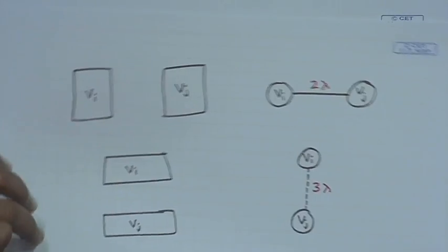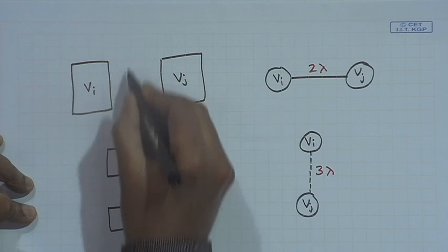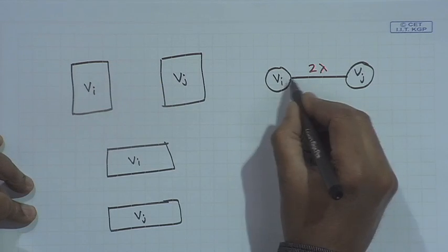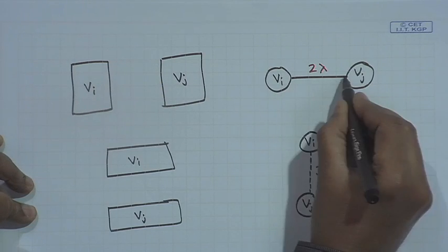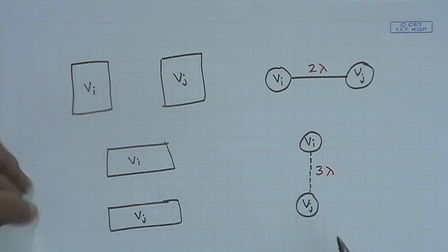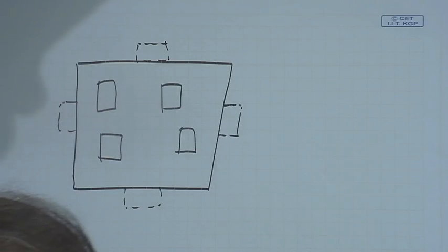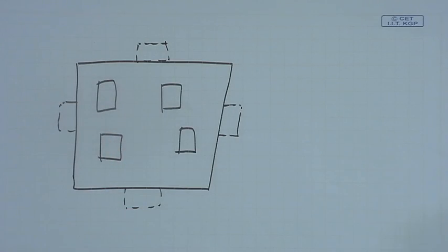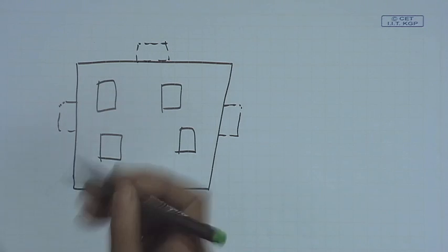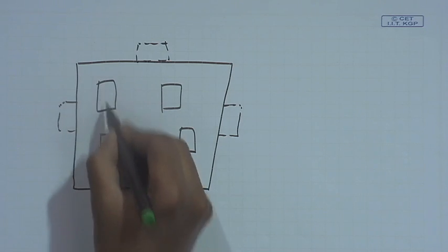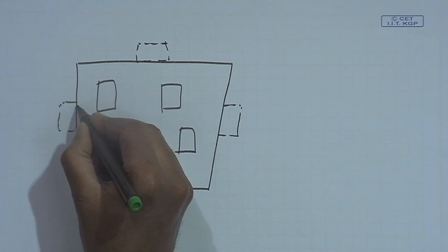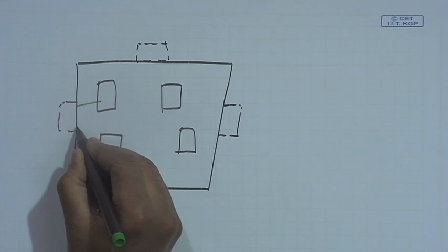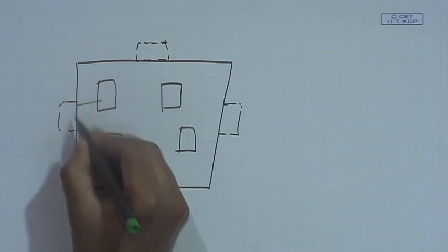You see, I said blocks which share a vertical boundary will have a horizontal edge, and the reverse for the other case. So, here which are the blocks having a vertical boundary? This imaginary left block and these. So, there will be a horizontal edge marked by solid.